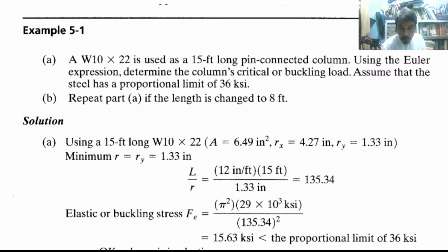Let's imagine a truss damaged by a truck. The bending of tension members probably will not be serious, as the tensile loads will tend to strengthen those members.